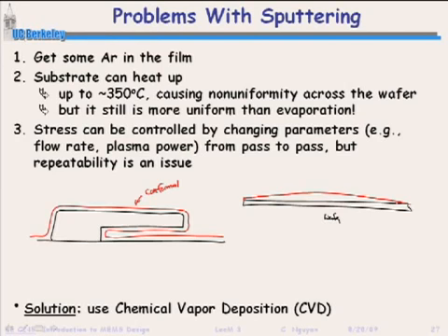And that matters a lot, because as we'll see later on, when we're going to etch this film, it's much easier to etch if this is uniform. Because now, since I've got parts that are this and parts that are this, I have to make sure I over-etch these parts here. And once I over-etch those parts, then once I've got rid of this film, now I'm etching the film underneath it. And that film better be able to hold up to that etching. And so it complicates a lot of things that your film is not uniform, but this is reality.